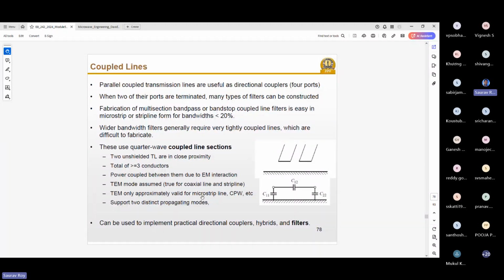You want to design wideband, you are saying? Directional coupler, with frequency band from 1 gigahertz to 3 gigahertz. That you can do generally using one only. Generally, a normal rat race coupler will give you good bandwidth. 1 to 3 gigahertz, I suppose it might be fine. You can design for 2 gigahertz and then you can get it actually.